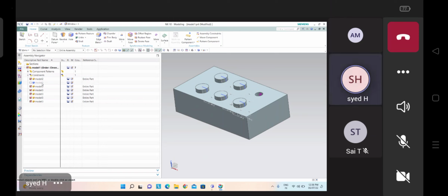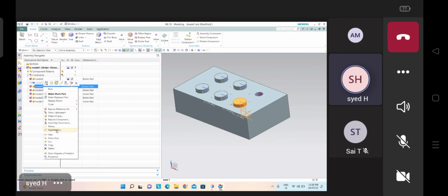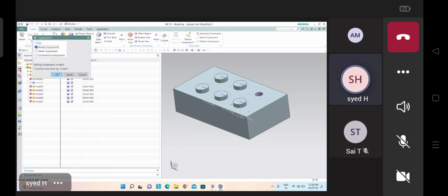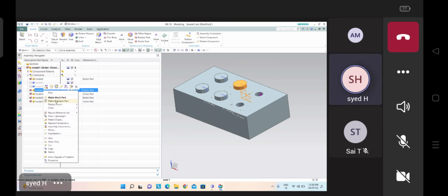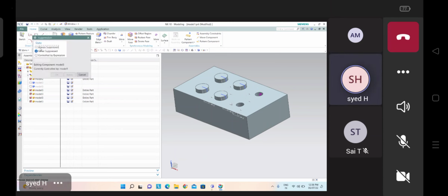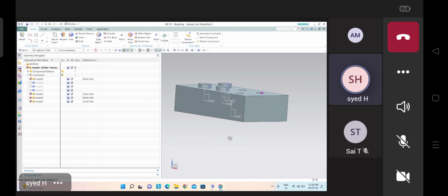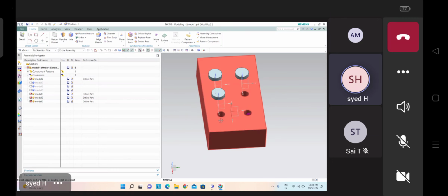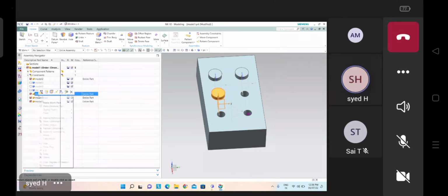The part is available in the library. Here in your part assembly library it is there, but when you come to the model side it is not visible there. And in bill of material also it will not show the part. So also I am making suppress, for example. These three parts are suppressed here. Now this is not visible here. Neither will it be visible in your drawing, nor in your bill of materials. Okay, remember this. Then make this one like a pack.